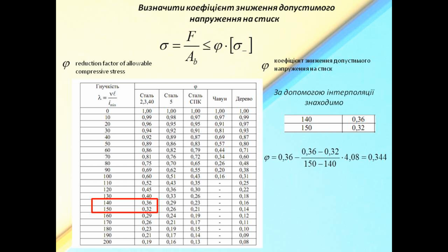Some machine design problems start with a known load and column length, and your job is to calculate the minimum diameter of a solid round rod to allow the column to survive buckling. Or you have to choose the appropriate cross-section area.